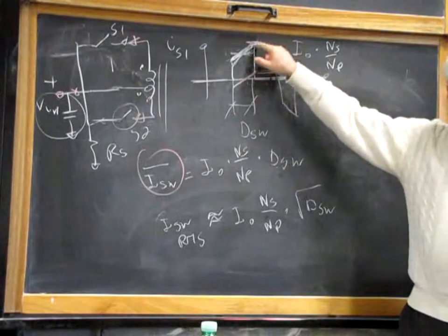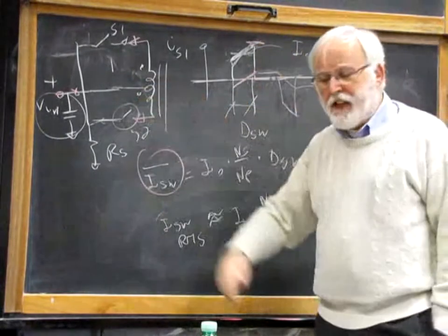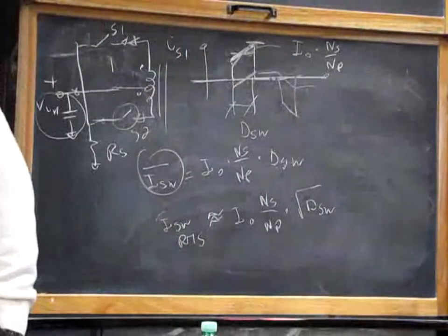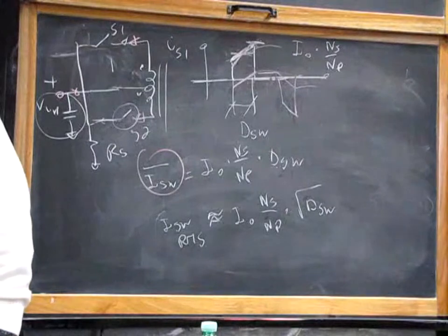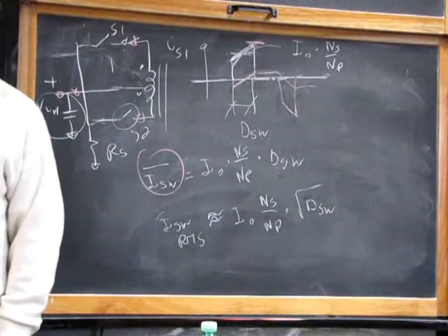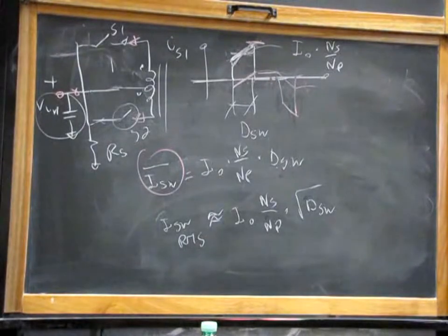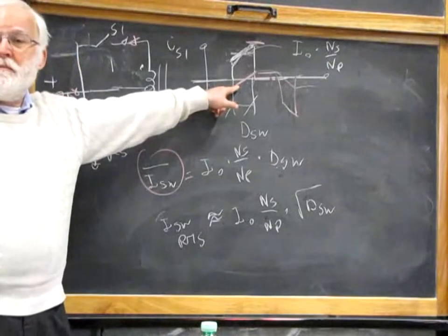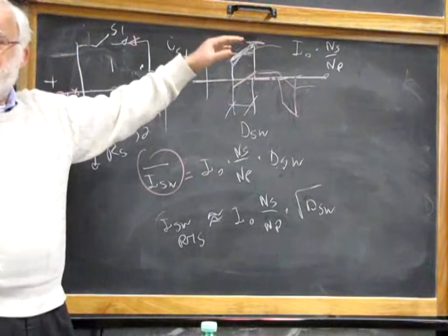But you cannot be very precise because in the first steps of design, you don't know yet what kind of transformer you will have. You don't know yet what will be your magnetizing current, magnetizing inductance. You can have a guess, but it's just an educated guess. Most of the time, this magnetizing current is absolutely negligible for stresses.